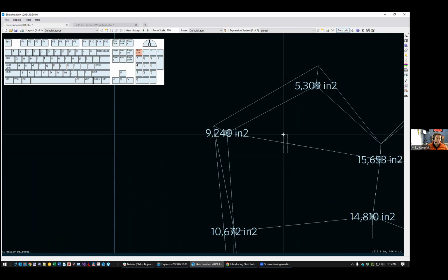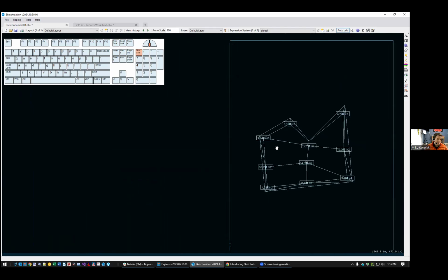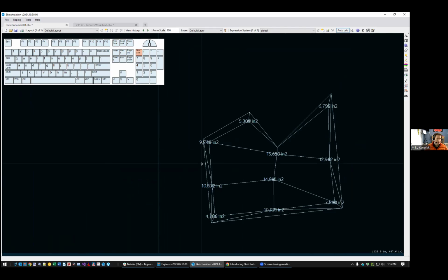It's very important. What it does is it looks at all of the shapes that come into that point, and it takes a quarter of the area if it's a 4-node shape, and a third of the area if it's a 3-node shape. So it's a very simple way of getting a trib. It's not engineering. It doesn't have engineering integrity, so you should be very careful about using this, but it's decent for a very quick estimate of a column load. So you can do it that way.